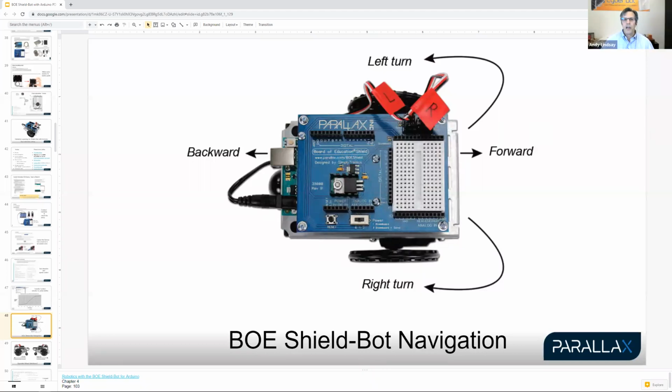One thing to check is we've got the breadboard on the right side of this picture here. And then there's the programming port and the tail wheel on the left side of the picture. So I'd like you all to take a close look and verify that that's the way that your robot is set up. The breadboard, the whiteboard with all the little holes in it, should be roughly between the front two drive wheels that are connected to the servos, and then the tail wheel should be on the other end.